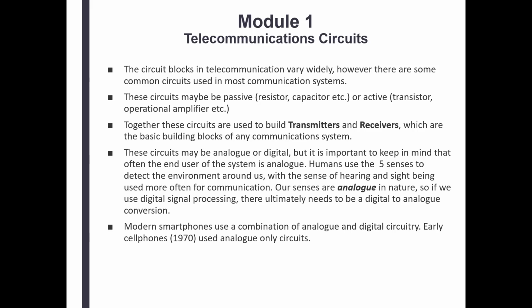You do need to supply power to, let's say, for example, an AND gate. If it's a 7400 TTL circuit, you need to supply the power to pin 14 and the ground to pin 7. Then that makes it an active component or active part because power needs to be supplied, right?